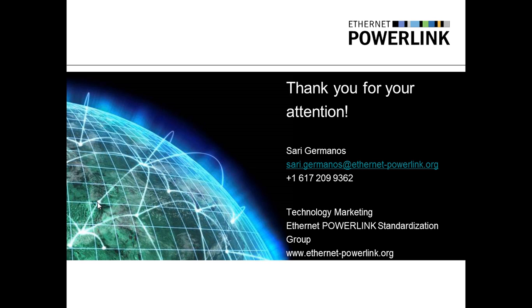Okay, and our last question is, how fast can the cycle time be? Yeah, so as I mentioned before, you can run POWERLINK down to 100 microseconds, and we've seen some specialized hardware people are running. This was actually in China. We have some machine builders running at 30 microseconds. I have no idea what they're doing with 30 microsecond cycle times, but they're doing it. But I've never seen any real examples where the architecture made sense to run that fast.